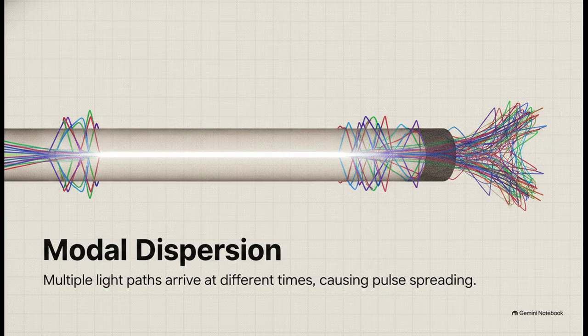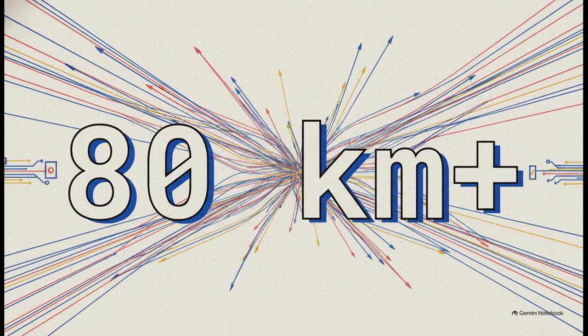and it forces some pretty massive distance limitations when you're trying to push high bandwidths. But single-mode fiber, it physically prevents that bouncing entirely. Because the core is so impossibly narrow, it only allows a single, fundamental mode of light to propagate. It just travels straight down the middle.